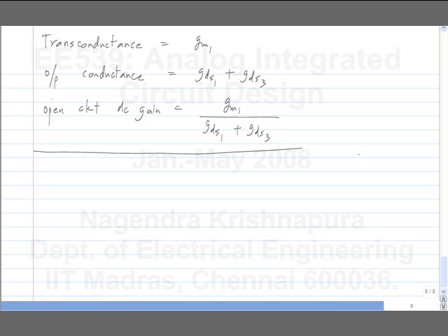You have to use long transistors for both NMOS and PMOS, because if one of them is dominating over the other one, it's not all that great. You have to reduce both of them to increase the DC gain. So just by keeping exactly the same current and going on increasing the width and length in the same proportion of all transistors, you will go on increasing the DC gain of the amplifier. What is the disadvantage of that? Parasitic capacitance. As usual, if you try to increase device size, you will increase parasitic capacitances.